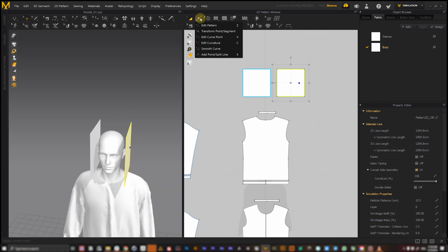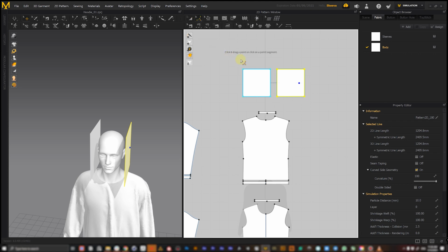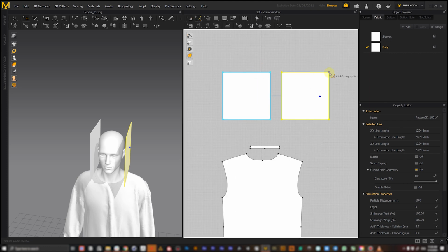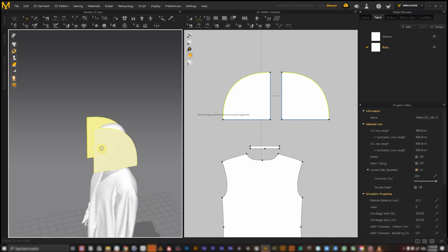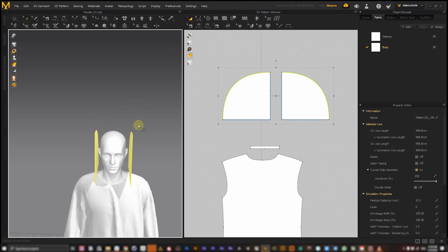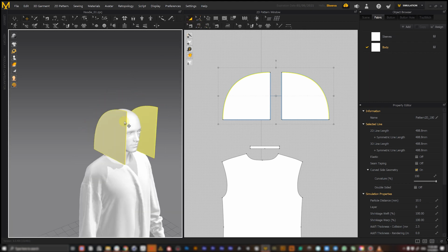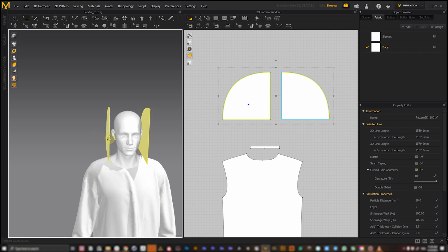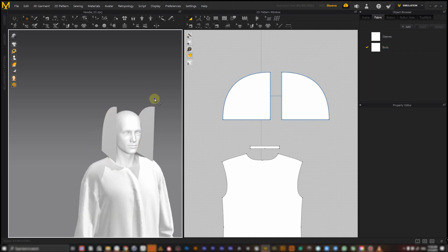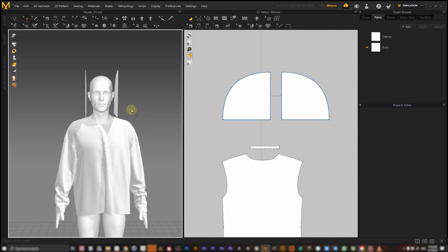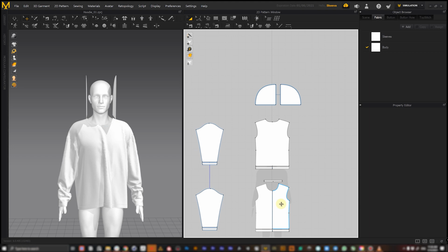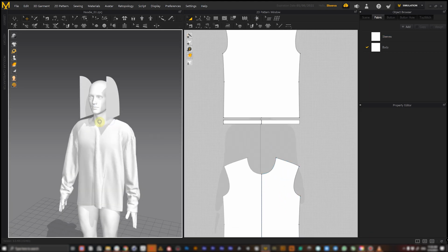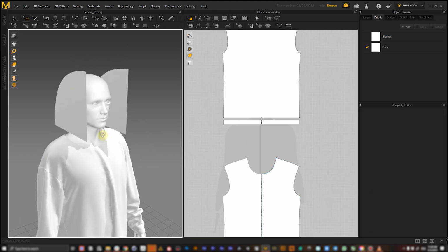Now let's select add point and select the smooth curve button, and let's drag one of the points to the maximum. What it does is it smooths the vector of the spline and creates a nice and round shape angle. This is exactly what we need for our hood. And also let's delete those neck parts that the modular system created for us. We don't really need those for our hood.